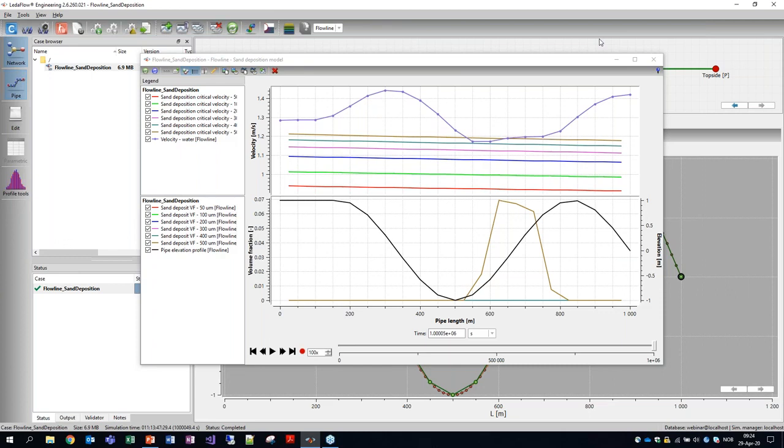Okay, that's that one. We're probably on the last. Scroll down. There's a few more questions. This is an interesting question. Does the sand model work in transient conditions? Which flow regimes? Does it work with slug flow, for example? Any issues? Yeah, it doesn't really matter what flow regime you have, because it's just based on the water velocity, basically. So it basically works for any flow regime. And I would imagine that in slug flow, probably the velocities might be high enough to keep the sand moving.